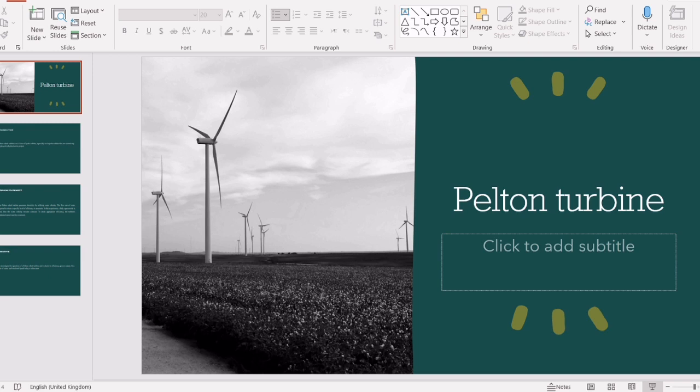The Pelton turbine is a very simple machine to build: a big circular disc supported by a revolving shaft known as a rotor. The buckets are cup-shaped plates that are placed over the circumference of the wheel and are installed on the circular disc. The buckets are normally set in pairs around the bottom.